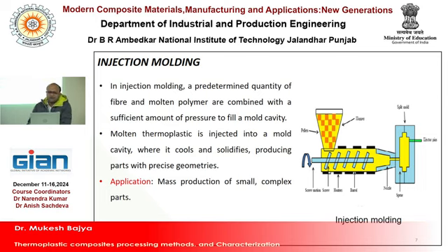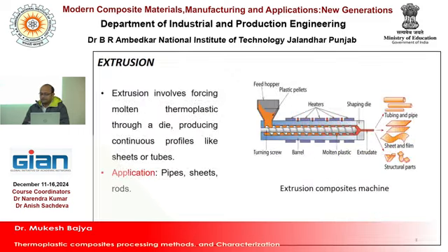Then extrusion techniques. From the extrusion technique you can extrude pipes like PVC pipes, or any thermoplastic matrix based pipes, and sheets, LDPE sheets, that is also a preform. These techniques can also be used for manufacturing preforms of thermoplastic composites, as well as some structural parts.